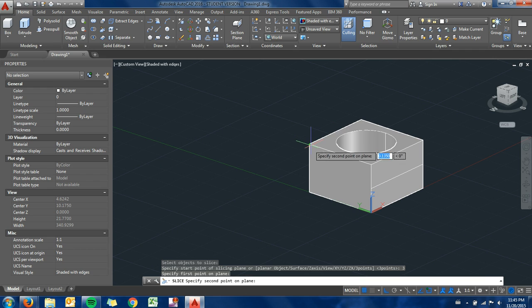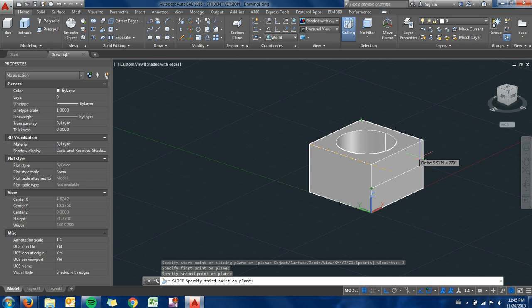So I will click this corner. I'll go to the end of this line I made earlier. I could either go up to this corner or I'll go here. So now what it's asking me to do is specify a point on desired side. I could keep both sides and it would turn into 2 objects and then I could delete one, or it will get rid of a side for me.